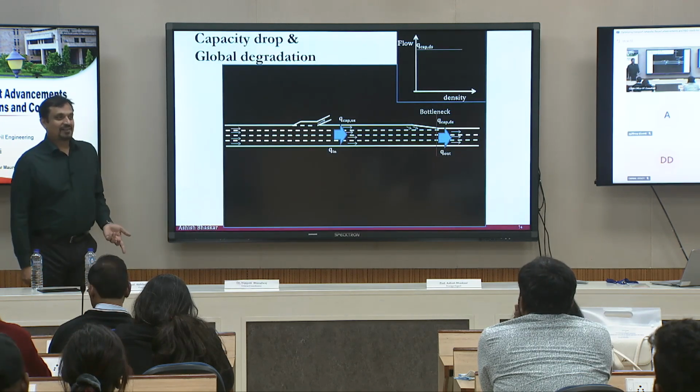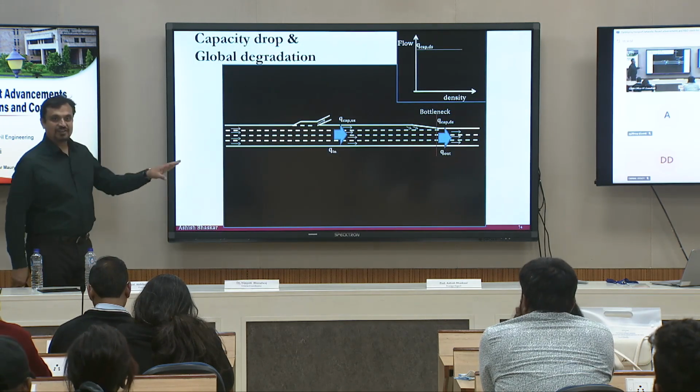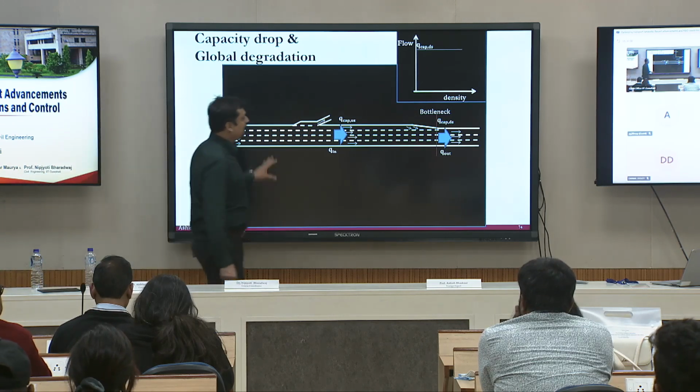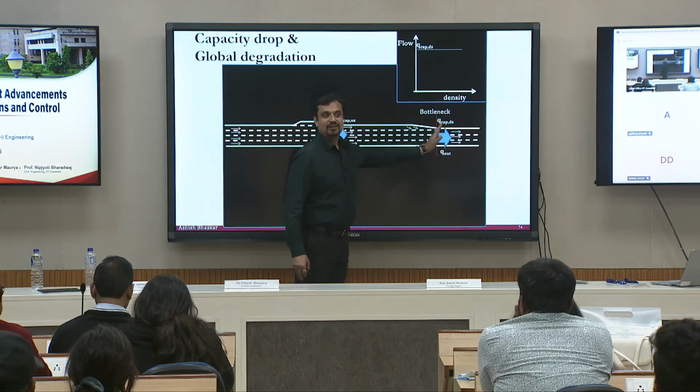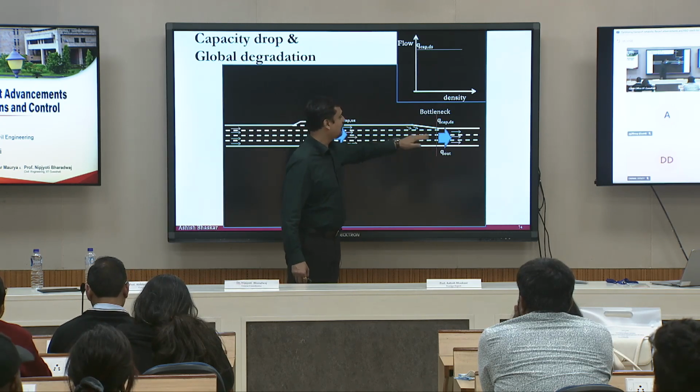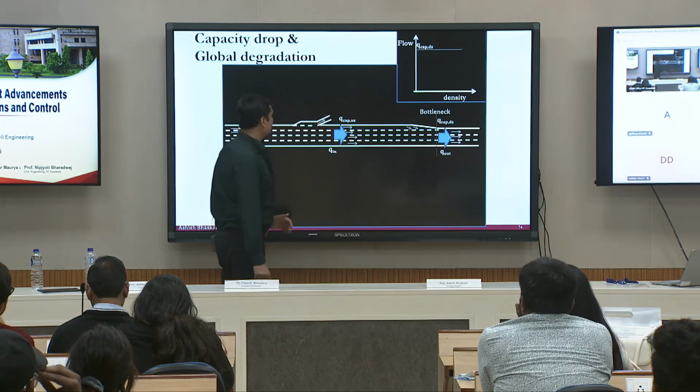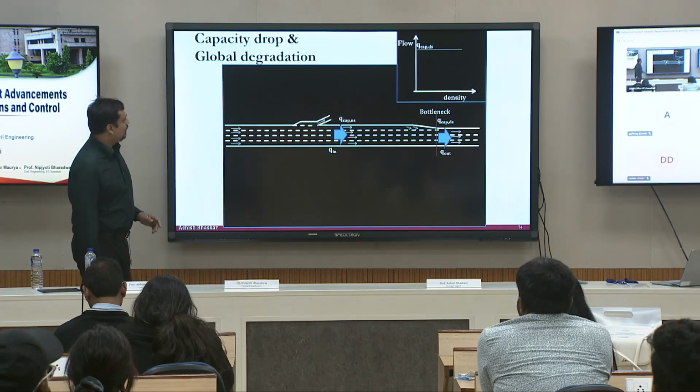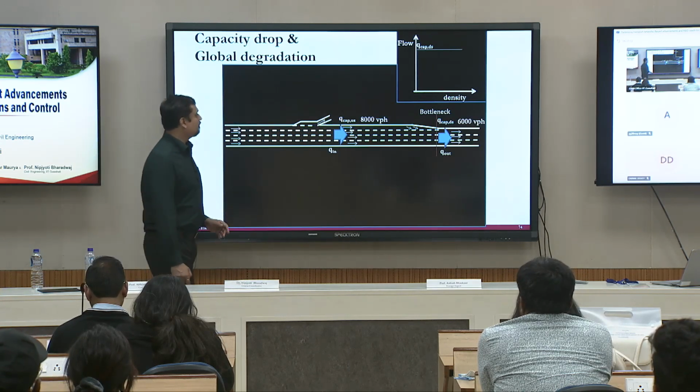Same concept. I'm giving you an example now on a motorway section. That's the bottleneck. Imagine the same as the funnel. Bottleneck from 4 lanes to 3 lanes. Let's say the capacity per lane is 2,000, for example. So we have 8,000 capacity upstream and 6,000 capacity downstream. It's a totally hypothetical scenario. Let's say your input is whatever it is. Let's say the input is 5,000.